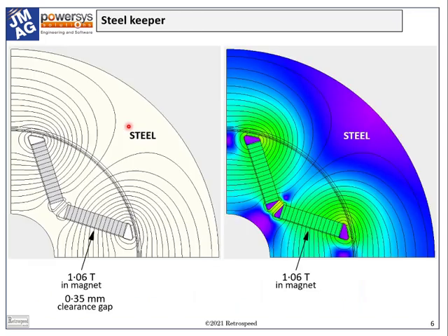And again, before we get down to business, here is another unusual finite element calculation in which the rotor is inserted into a keeper. That is a close-fitting steel tube that constitutes a magnetic shunt or short circuit around the entire rotor.